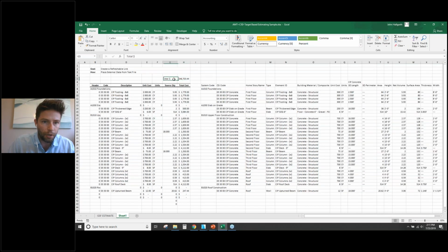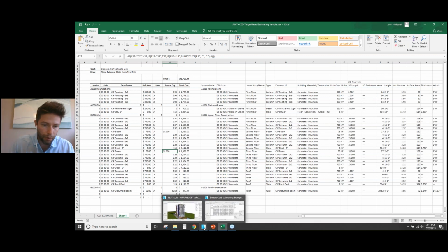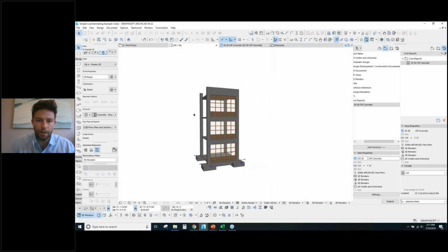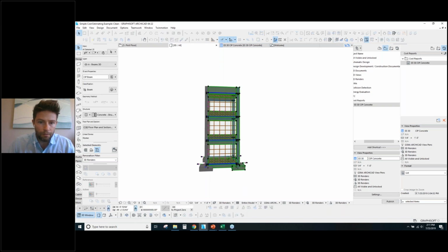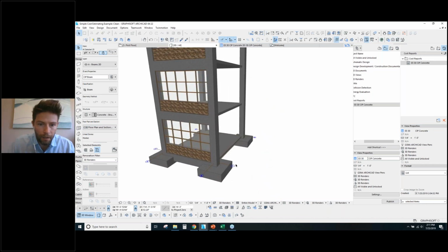So now we have a total cost, and we've set up this link where we could then go and continue to work in our model, update our unit cost, change our units if we wanted, and this will automatically calculate for us. So let's play with that just real quickly. So let's just go to 3D, and let's just grab essentially everything in our project that's not including what's on the column line. I'm going to deselect our little grids there as well.